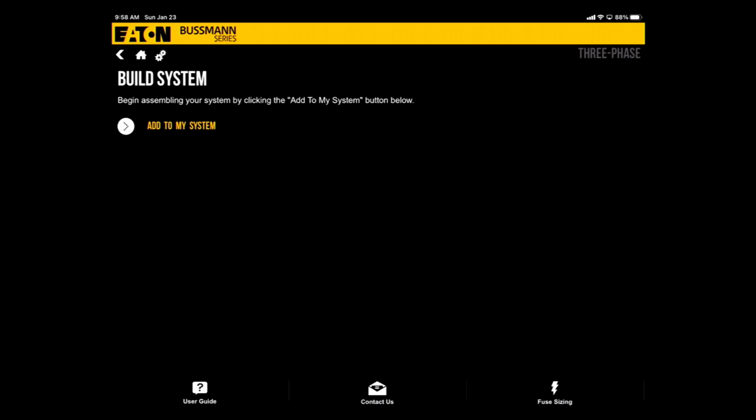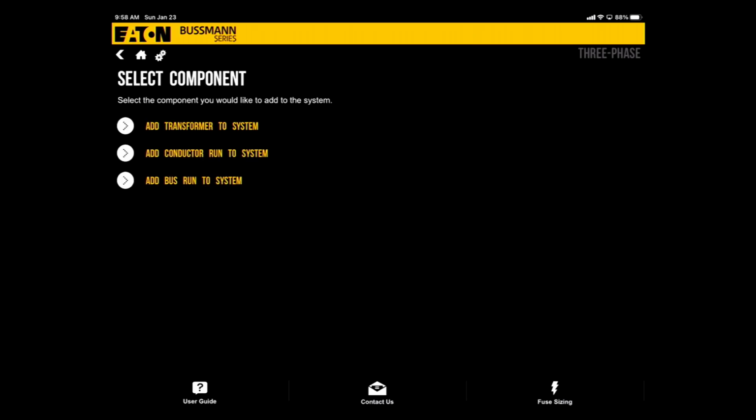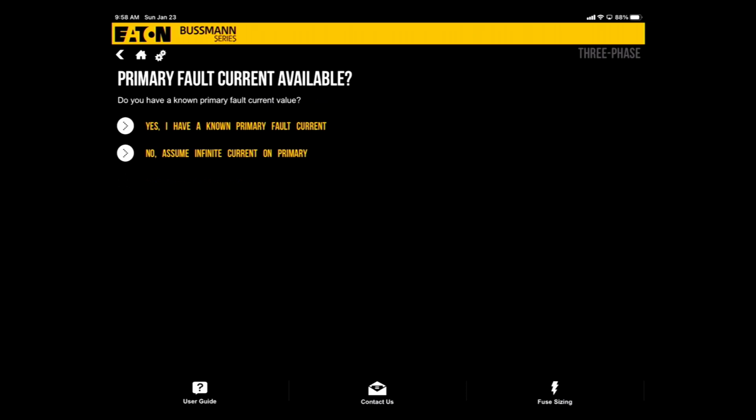All right, so I'm going to click Add to my system. I'm going to add transformer to the system, and I have two choices now. It says, do you have a known primary fault current value? Yes or no? So I'm going to select no. So I'm assuming that we have something called an infinite current on the primary.